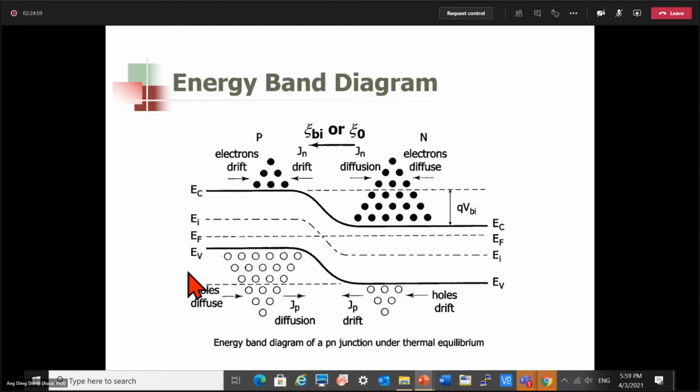Okay, so on the vertical axis, when you go up the energy axis, the potential energy axis, you go towards potential energy of 0, right, you also go towards the potential of 0. Okay, all right, vertically. Now, if you move downwards vertically, you go towards more and more negative potential energy for electrons, and therefore you move towards more and more positive potential.